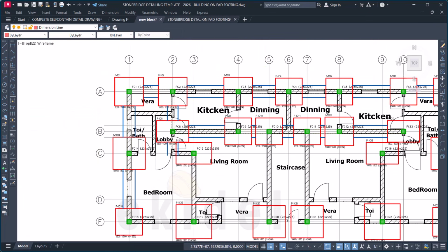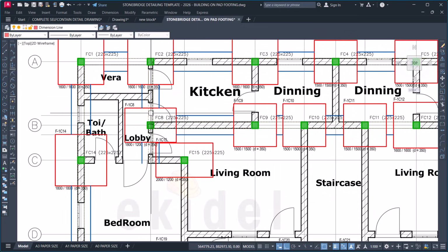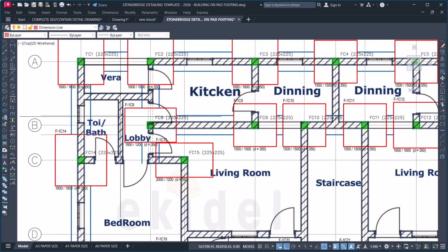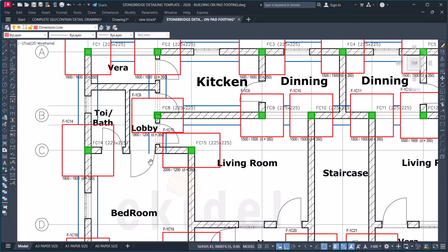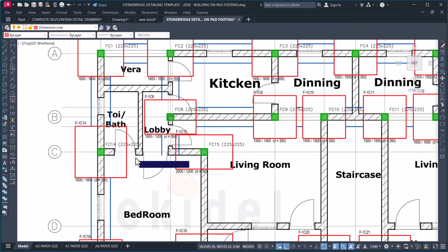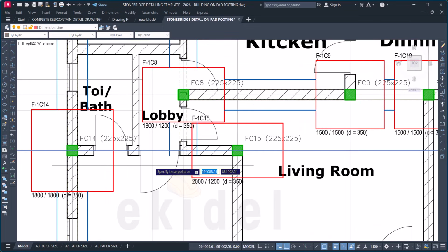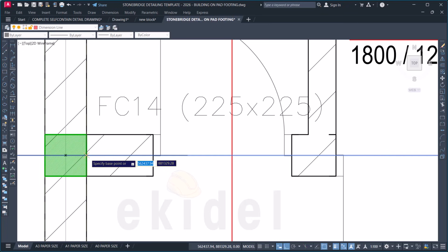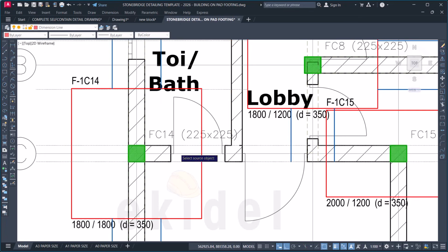For your foundation layout, you can choose not to provide digging for every place. At least it will also help to reduce costs for the client. While the other smaller walls, for example toilet walls, can sit directly on the DPC slab and nothing will happen to it. Okay, that's fine. So with this now, I'll come again, enter and offset. Copy this first, and then this is also a major wall. So I'll also come here, click on this, and then keep here and keep here, enter, match property with this, and then this and this.